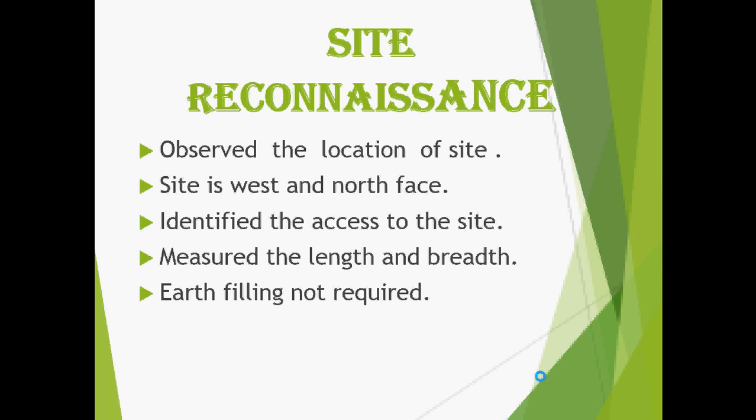The site reconnaissance has been made. We have observed the location of the site. The site is west and north facing. Identified the access to the site. Measured the length and the breadth, and earth filling was not required.